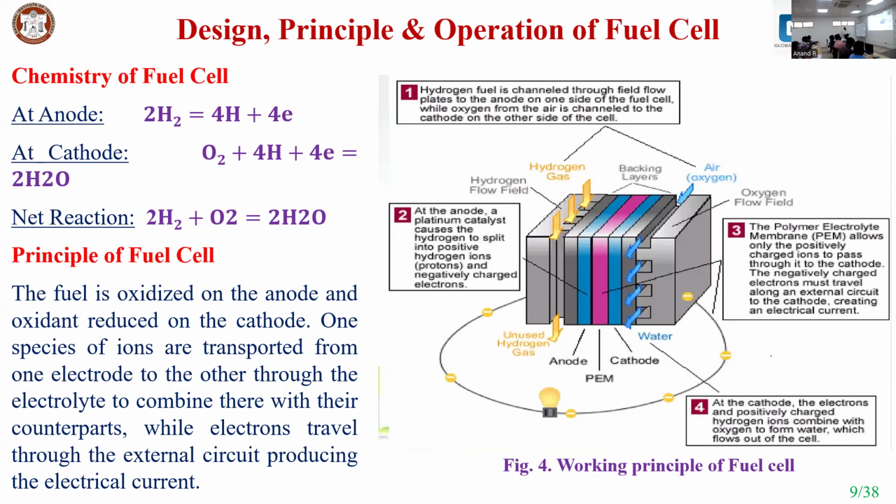So you need to select the proper geometry of the flow channel based on computational analysis. You model the different geometries and ensure which cathode flow geometry or anode flow geometry, as well as water removal, is best suited for getting the best electricity out of a square meter of the flow path.